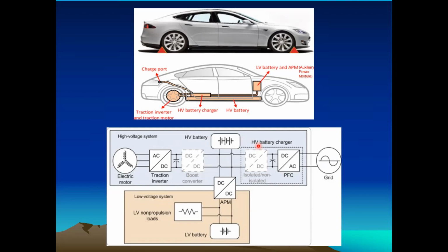For example, in a television, you are first converting the 230 volt single phase AC to DC, which is again converted to various levels of DC using a DC-DC converter. Or if you take the laptop, you have a battery which is already charged from the mains. Now it needs another DC-DC converter for getting different levels of DC voltages inside the laptop. The digital system needs some 3.3 volt. The motor for the drive needs 12 volts. Like that, so many different levels of DC voltages are required even inside a laptop, which is derived using a